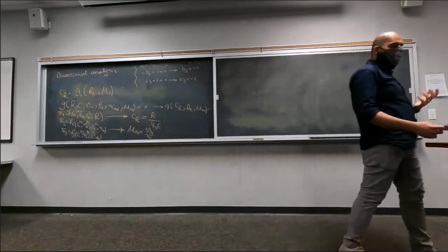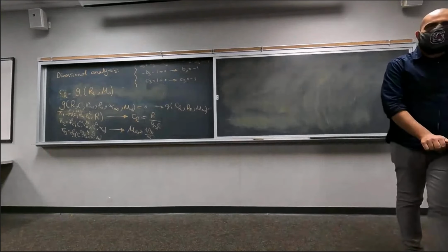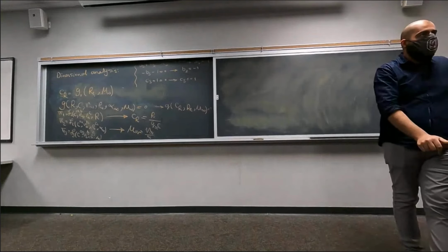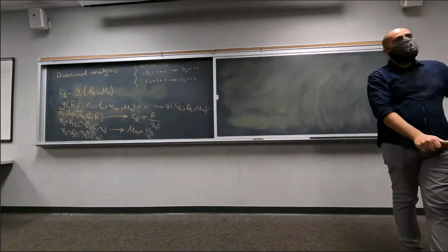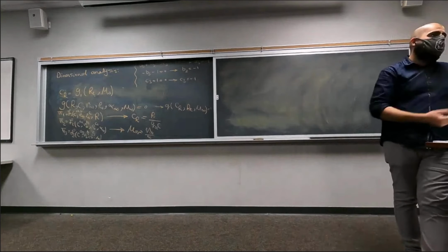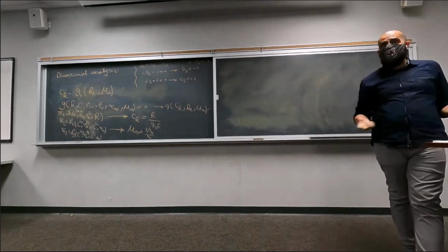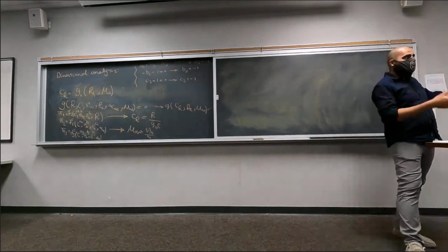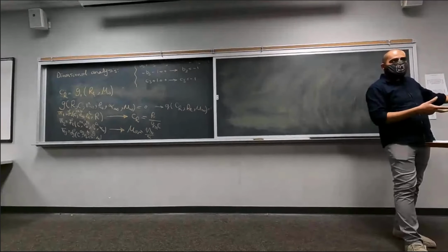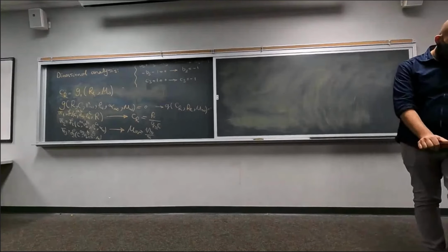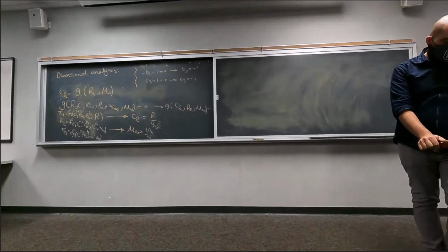So what does this mean? It means that if you do that dimensional analysis, come up with the dimensionless parameters that are important in your analysis, you can actually run tests in a wind tunnel for a scaled down version of your plane, airfoil, whatever, and apply the results to the real flow condition, right? That's the main idea of the flow similarity. It makes the Buckingham Pi theorem even more important.